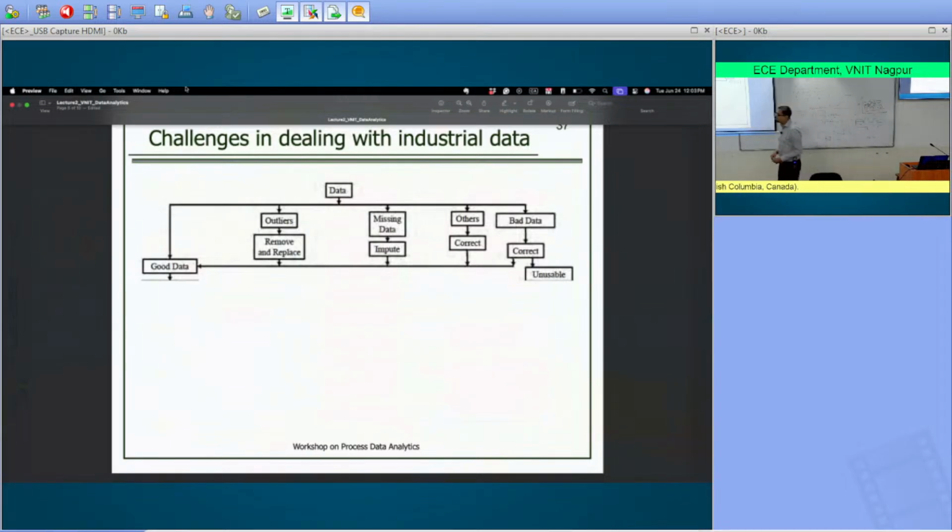And often outliers are just way off where your measurements are expected to be, and they appear and then disappear rapidly, right? So inherently, some of these systems have an inherent time constant. So the level, for instance, cannot do this. It cannot go like this and then come back. Right? That doesn't happen because it has an inherent inertia, a time constant. It never goes up that fast or comes down that fast. So that particular data point or data points here must be outliers. Right?